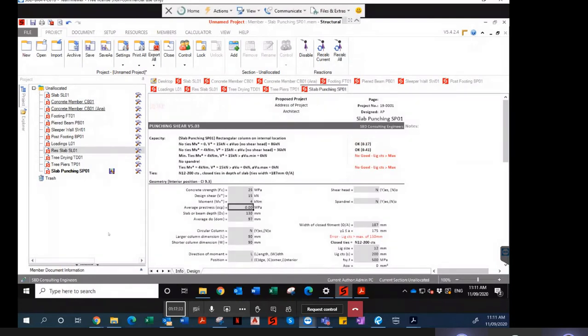You look at your shear capacity in here. So your phi V is 36 kilonewton. And this one here is more for your beam, so that's why it's got legs in there. In our slab, we don't have any ligature. Does it make sense? Yeah.